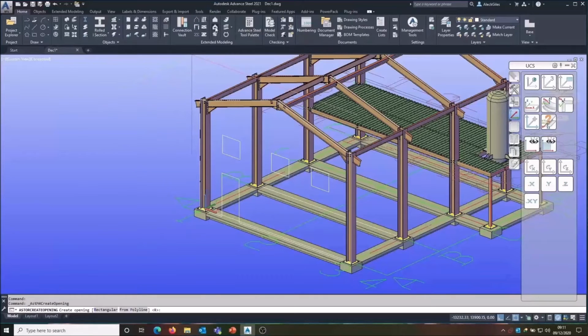What you can see now is an area object. I'm going to define the openings again. I'm going to say from polyline. And you have to pick the area first, remember. You would expect to go and pick the polylines, but you have to pick the area first. Now pick the polyline. You can pick multiple openings at once, so I'm going to pick all 3 polylines for the openings at once. It's no problem. Do you want to delete them? Yes, absolutely. Always say yes to delete them.